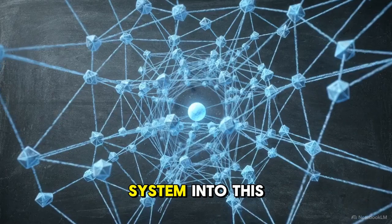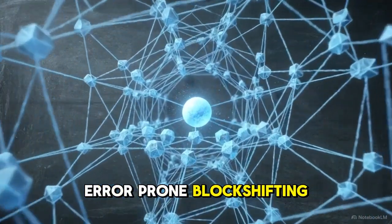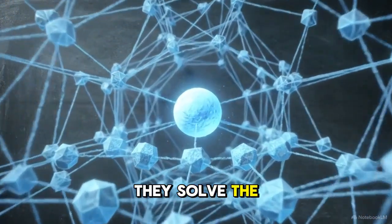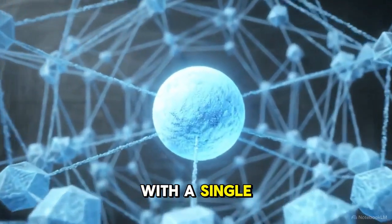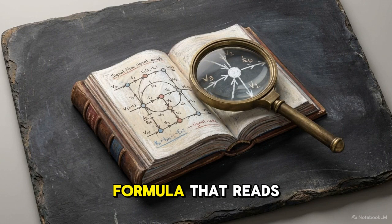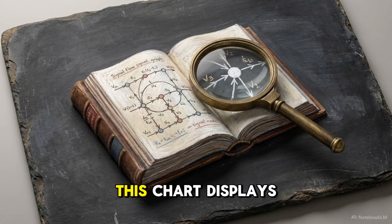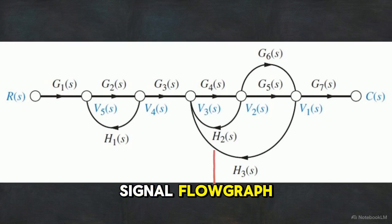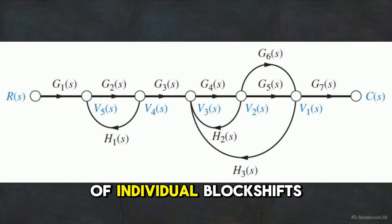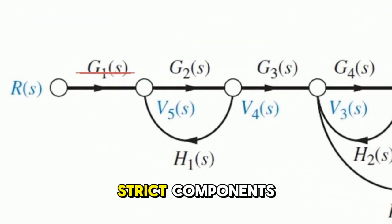By converting the system into this lightweight architecture, engineers can abandon error-prone block shifting entirely. They solve the entire network simultaneously with a single equation. That equation is Mason's rule. It's an algorithmic formula that reads a signal flow graph and computes the overall equivalent transfer function in one pass. This chart displays a multi-loop signal flow graph. Attempting to reduce this manually would require dozens of individual block shifts. Mason's rule handles it by breaking the map into 3 strict components.